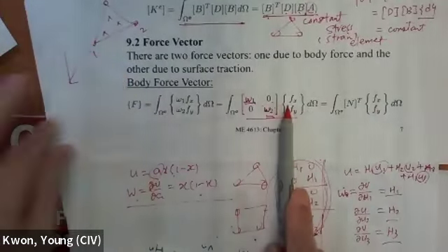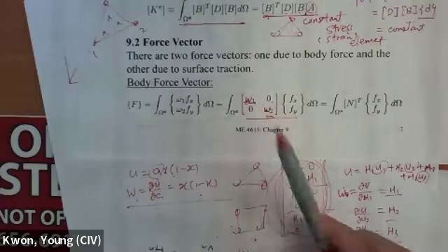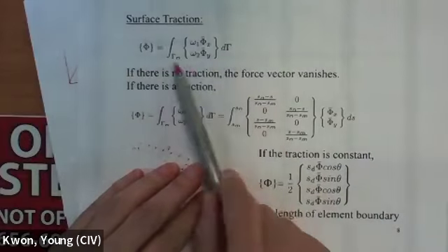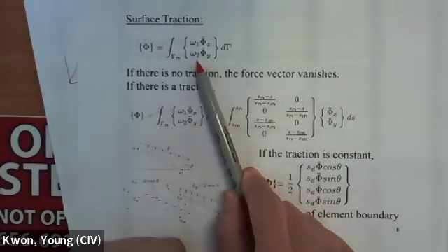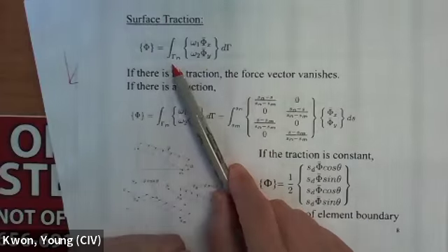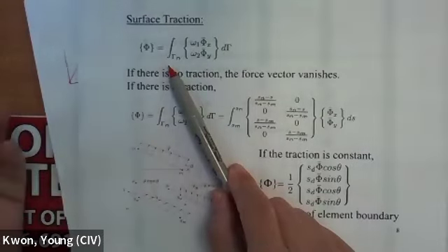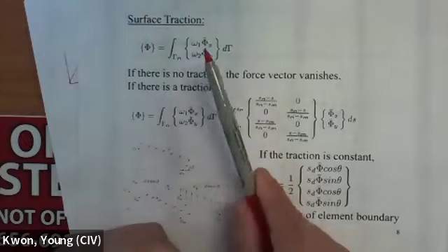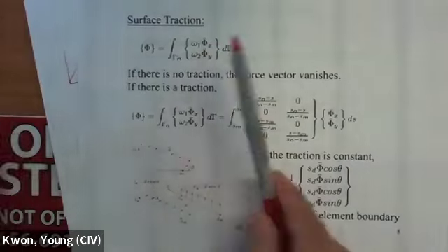So that's the body force. Now, the more important part is going to be the traction, the surface traction. So this exactly looks like the heat flux in chapter 5. The flux and traction on the surface of the body. But now the difference between flux and traction: flux is a scalar quantity and traction is going to be a vector quantity. So you have to differentiate among traction in the x, y, and z directions; you cannot add them together.